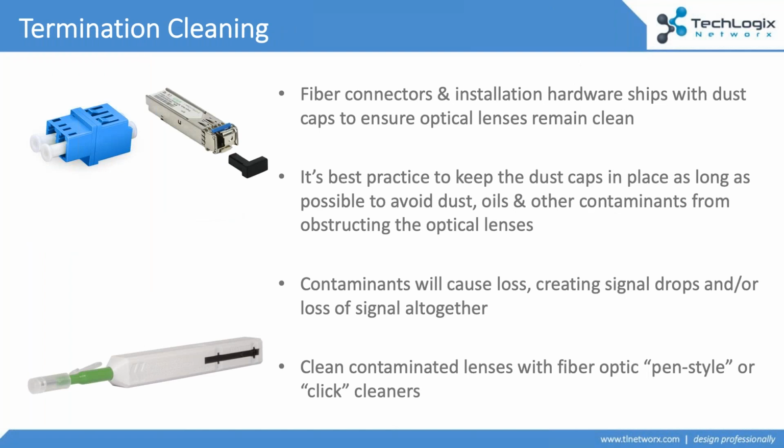Let's talk about cleaning your connectors. This is a big deal, and this is a big tech support issue that tends to come in. People plug in all their installations. They know they got good connections, but they're having issues with their signal. Now, fiber optic equipment, couplers, SFP modules, extenders, all of these devices, they ship with dust caps. Okay? Best practice is keep the dust cap on the device as long as possible. It keeps the optical lenses clean.